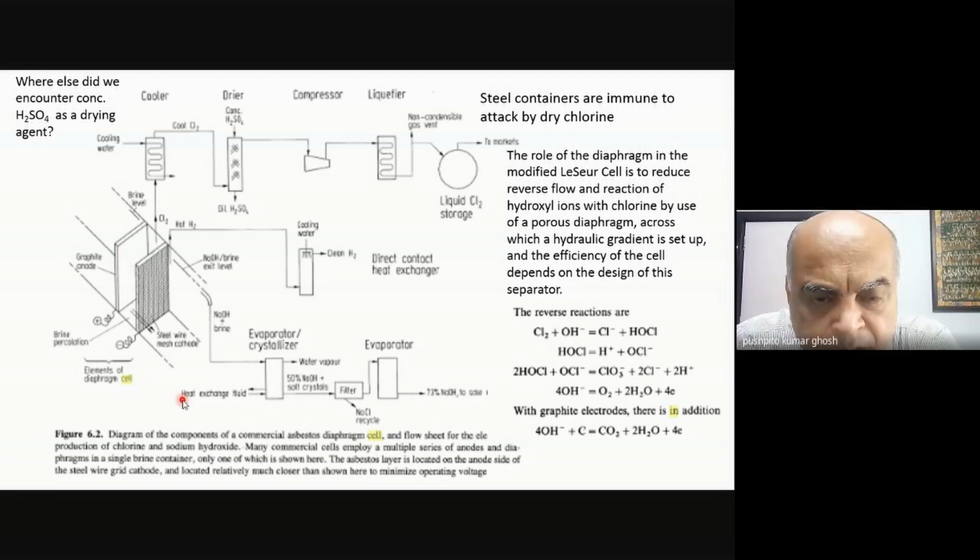Chloride was unreacted. Well, at the point that I'm trying to recover sodium hydroxide from the cathodic stream, obviously that sodium chloride will be a contaminant. So I'll have to make sure that I am able to remove it. Otherwise, I'll have sodium hydroxide laced with sodium chloride. People may not want that. So obviously there were complications introduced downstream, which would involve a better separation process to remove sodium chloride from sodium hydroxide. But what they said is that is a lesser price to pay compared to the back migration of the hydroxyl ion. Is that clear? The compromise?